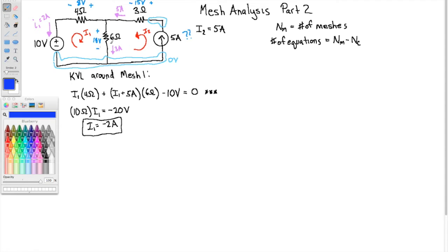So if we had an increase of 18 and then an increase of 15, then from here to here is an increase of 33 volts. Right? So what's the voltage across the current source? Well, if this is 0 and this is 33, then the voltage drop is 33 volts.